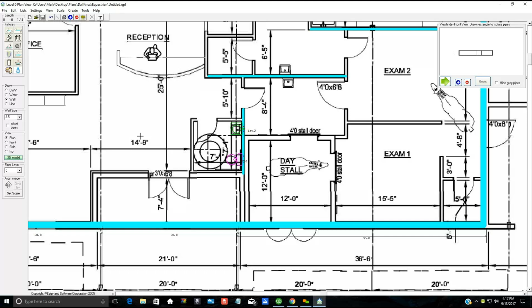What I would do from here, I'll just position a couple of these walls here. I have a wall here that appears to be 2 by 6. I have to figure out what the width of that wall is. The architect didn't give that to me right here, but assuming that this is a 6-inch wall, nominal 5.5.